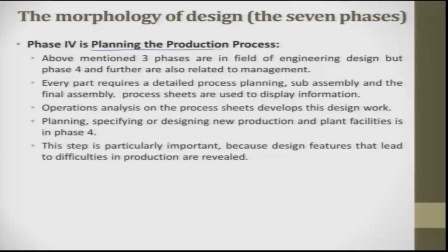Next is, as I said, planning the production process, because now that you have fixed the engineering specification and engineering design constraints, what you do is look for manufacturing processes. By the way, the manufacturing process can also go back and say, oh, this is not possible, we cannot make this design. Can you make an oblong shaft instead of a circular shaft? Very difficult, you can't make a process. Can you make a square shaft instead of a circular shaft? And the detailed design says a square shaft has to be made. It is pretty difficult for a long one. If you want to do extrusion, possible, and again in extrusion also square edges are very difficult. So, people always try to go back and say, no, it is not possible. So, can you convert this square into a circular one?